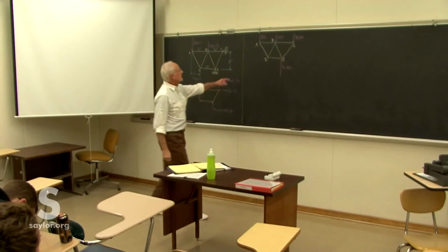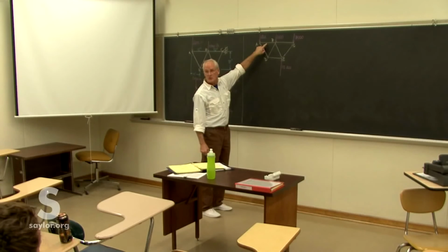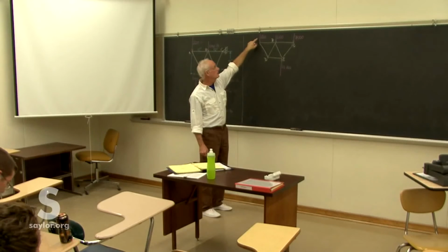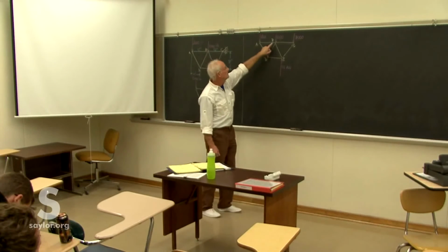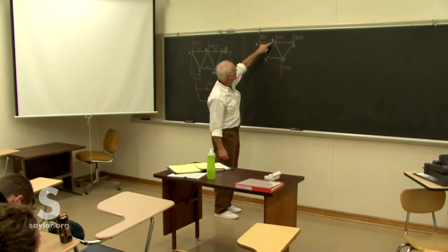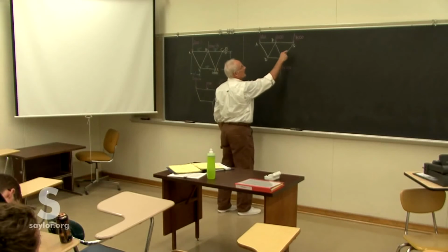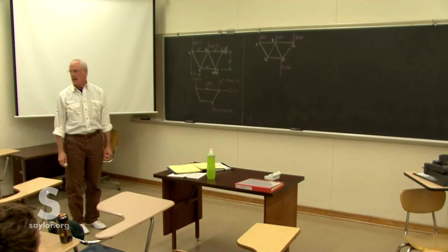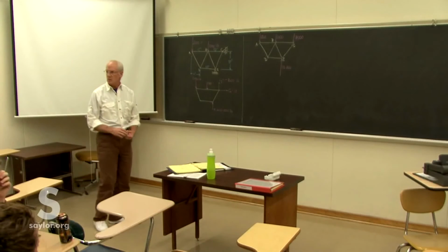So notice that at joint A, we have two unknowns. We don't know how much force is coming from that member. We don't know how much from this member. And we have one known. Joint D, three unknowns, no knowns. So we certainly don't want to start there. B, one known, 1, 2, 3, 4 unknowns. So we definitely don't want to start with that one, and so on. So we can either start at C or at A. It doesn't matter which. Both have two unknowns and one known, so it's 6 of one, half dozen of another.